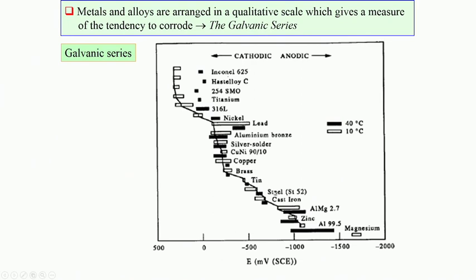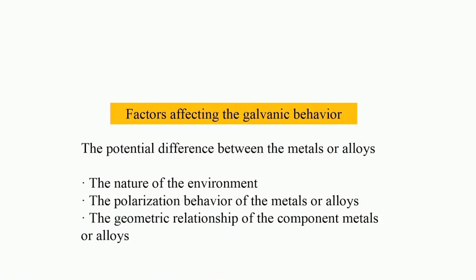But if you couple steel with aluminium bronze or steel with nickel, you will find a lot of corrosion because of galvanic corrosion. Similarly, if you choose zinc and titanium or zinc and stainless steel, there will be a lot of galvanic attack. So, whenever you choose material combinations, the galvanic series plays a very important role and acts as a guideline for the choice of material combination for a specific purpose.